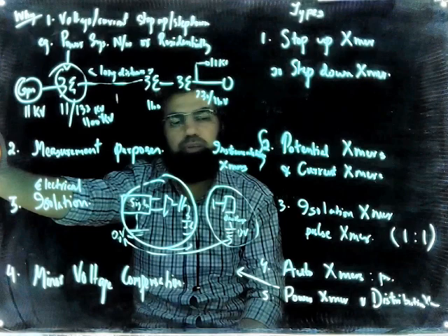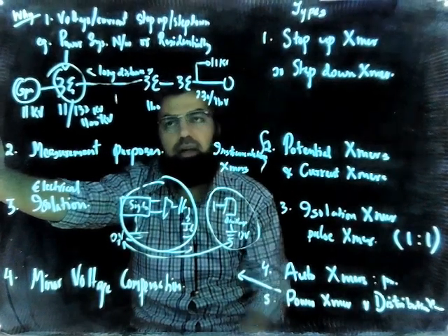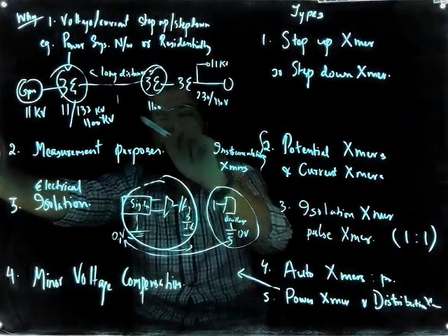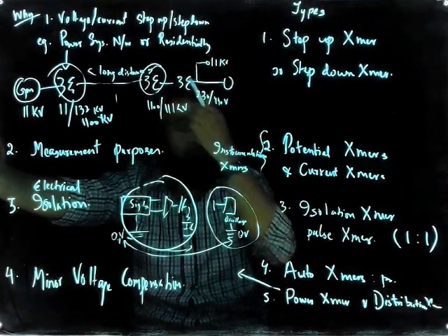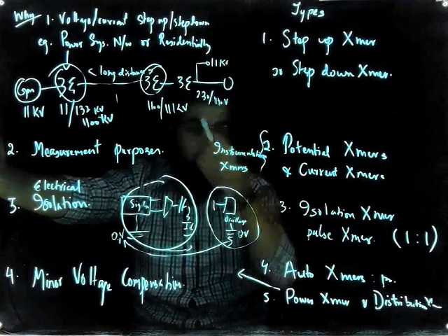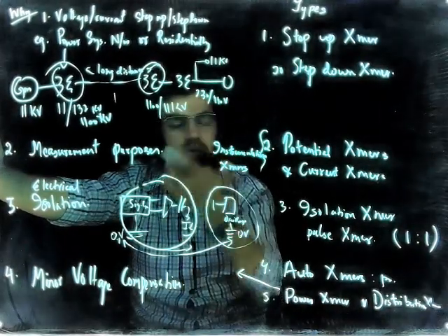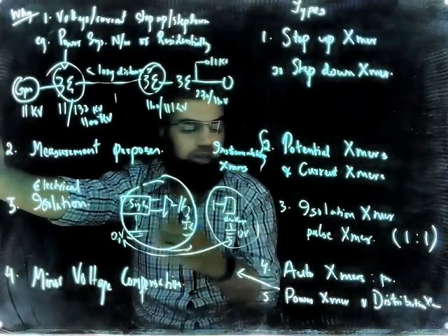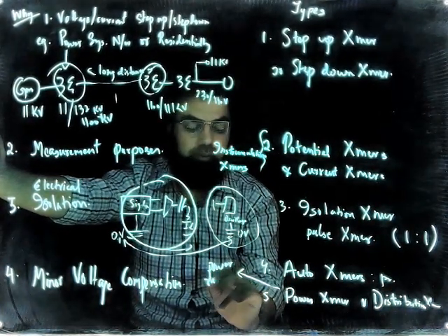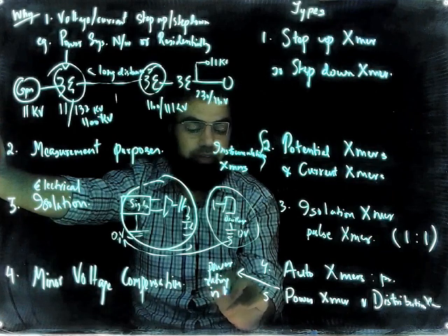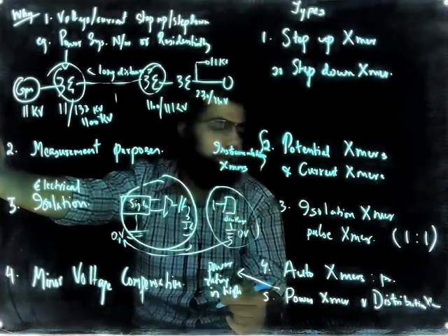The power rating of such machines is very high, and similarly the transformer that will reduce this voltage from 1100 to 11 kV back, or 33 kV, whatever, will again be a power transformer. The power rating of this transformer is high, so it can be greater than 200 MVAs.